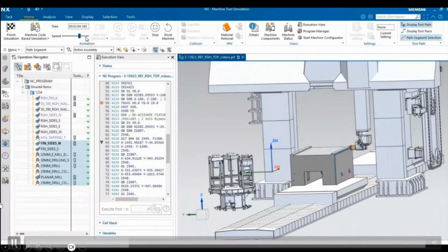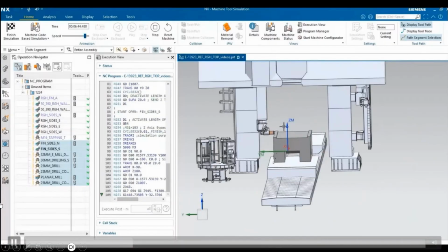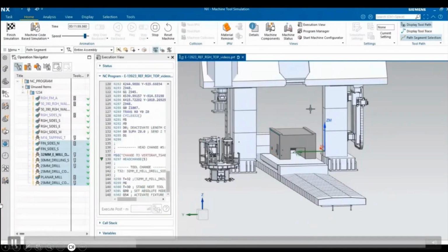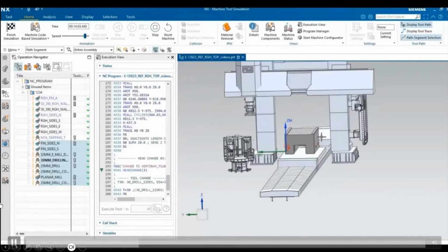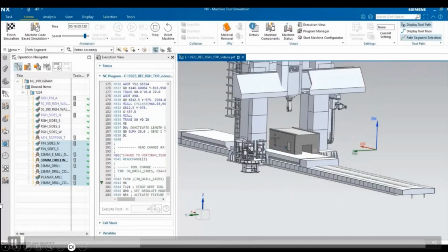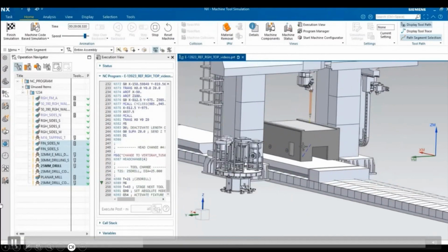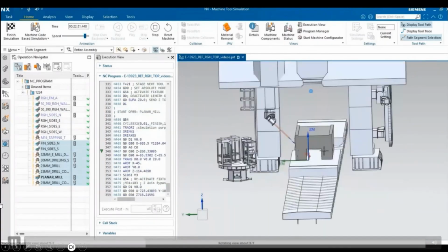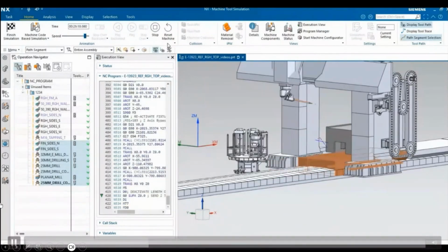You can see how it's in this direction while it's cutting this side of the part, but as it rotates around, you can see the axis direction changes on this head. Now the next couple of heads, there's some basic right angle heads with different configurations. Okay, and those are going to finalize those. Now, finally, another full 5-axis type of head to get into some of those really tight areas. There's some different operations for that.